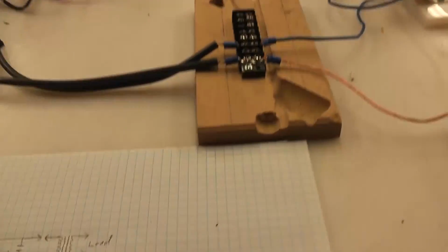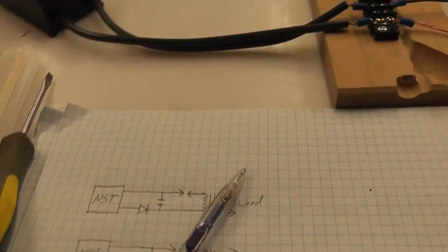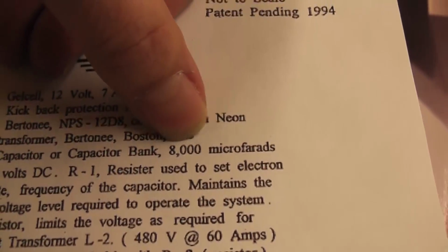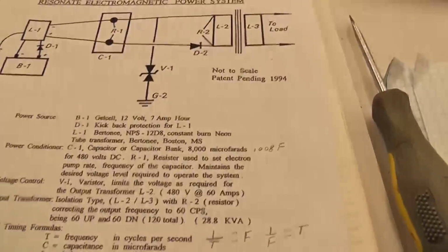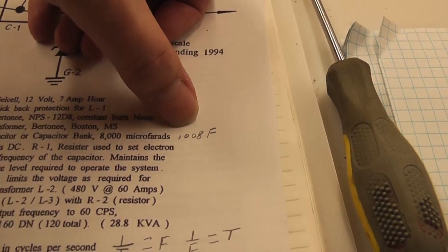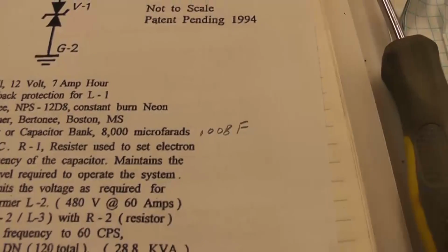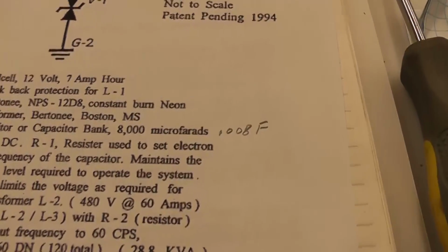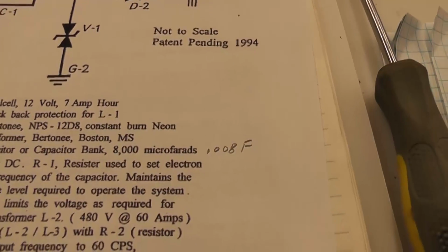But the next thing I was going to say though is this capacitor here, the value of it. The thing that Don says, or whoever wrote this says, is he has 8,000 microfarads. That just sounds like a huge amount, right? Well, it's not. It's only 0.008 farads. If you ever worked in the car audio industry, you know that they use 5 farads when they're putting together those stereos. I know I used to do that, actually. 5 farads, not microfarads, but whole number 5. Huge, right? Well, just to get one that's 0.008 farads is actually expensive because of the voltage rating you need.